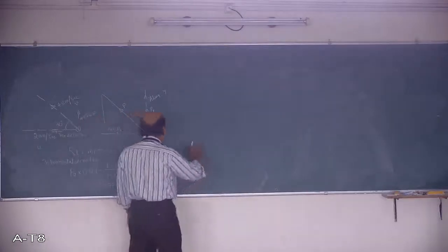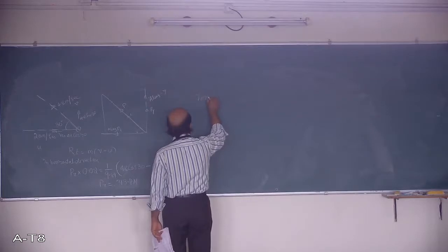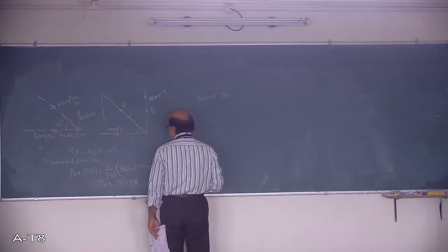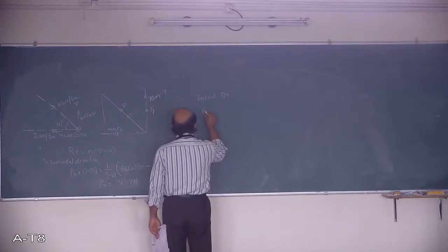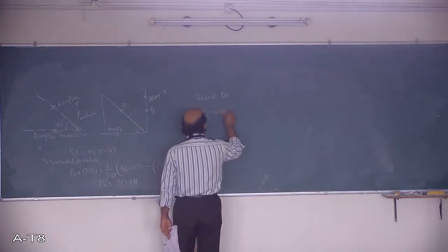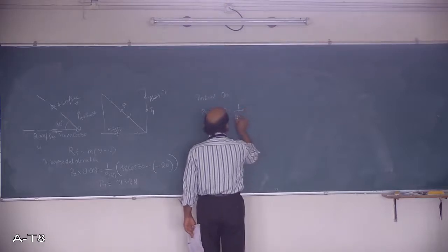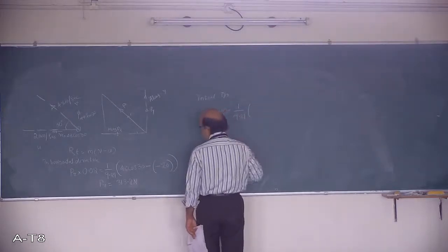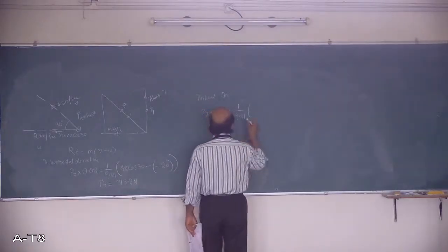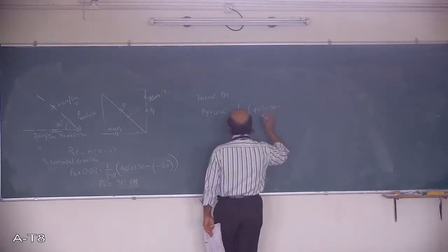Next, in the y direction, the vertical direction, I also have to work out Py, the force applied in the y direction. So in the same equation, Py into contact time, the same 0.02, is equal to the mass of the same ball divided by 9.81 into the vertical direction final velocity, 48 sin 30, minus the initial vertical velocity.